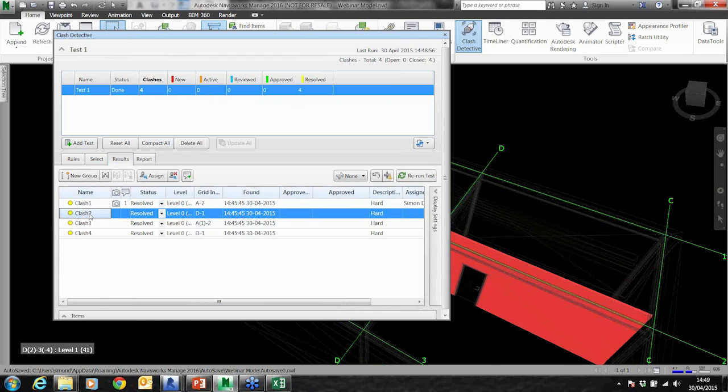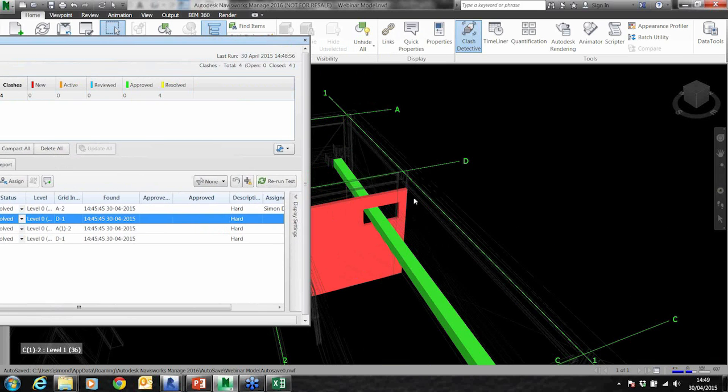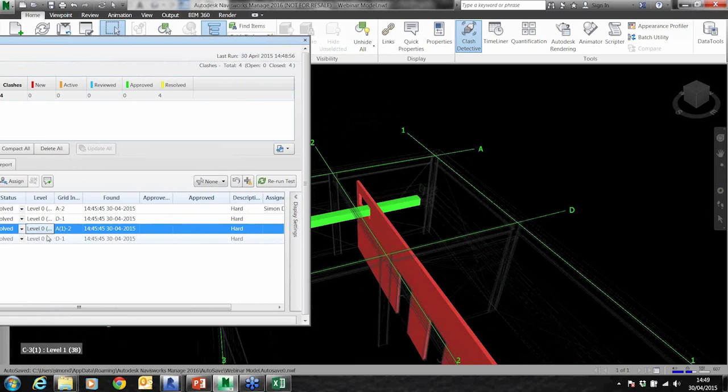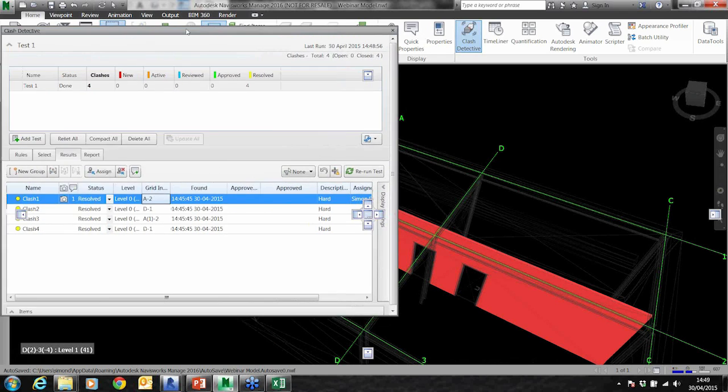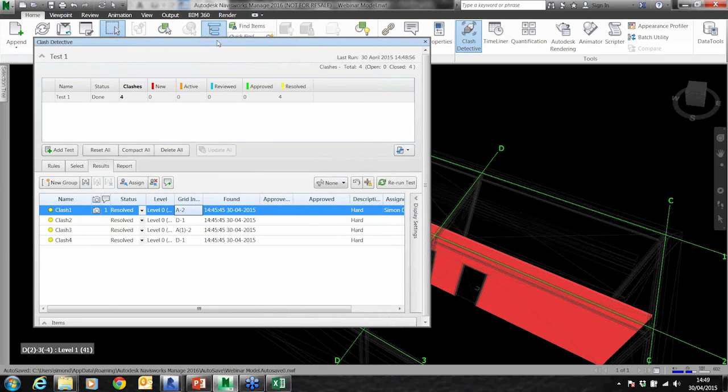So now we've all gone to the correct color, and what we should be able to see now is we've actually got the hole in there. It's displaying correctly in this view for some strange reason, but we've now got the clash detection working. Okay, this is a very, very powerful feature. It is the only difference between Navisworks Simulate and Navisworks Manage is this tool. But on a very complicated project, this has obviously been done quite simplistically, but we can start to not only find the clashes, but we can then manage the process of fixing them. One of the features I do like is if you rerun this check and it finds a new clash, i.e.